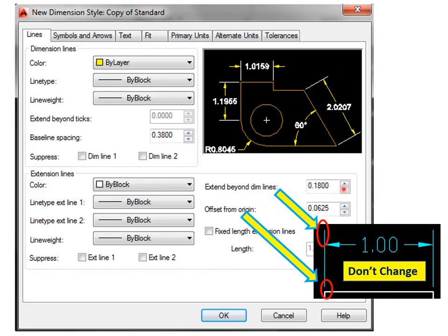Okay, another thing I wanted to point out here is, again, we are in the Line tab. These are already set for you. If you want to change the length of the extension lines beyond the arrowhead, here it's set. Again, there's no reason to change this, you just leave it alone. It's following a standard, whether it's American or international standards.